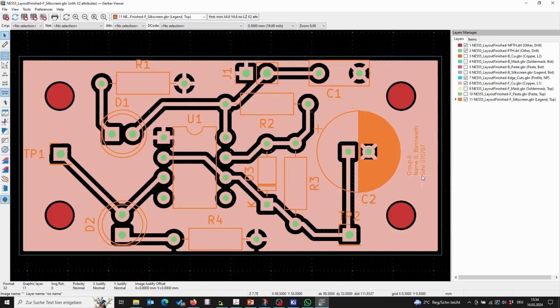And if you put here all the revision number and stuff, you can be sure that what you generated in KiCad is the same revision in here. Okay, that's all about the KiCad Gerber generation, drill file generation, and Gerber viewer.